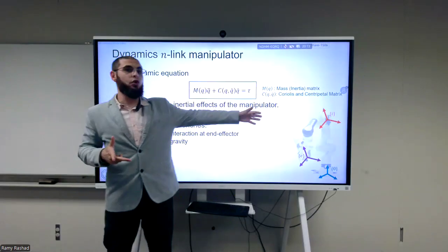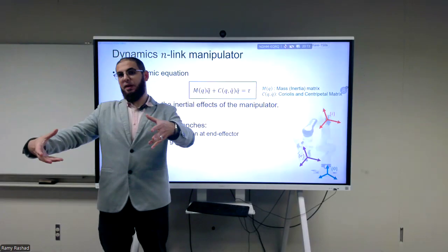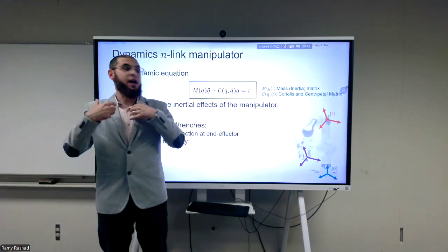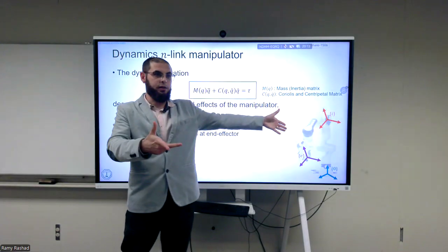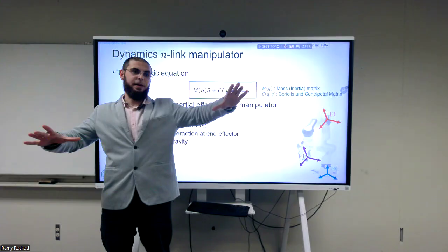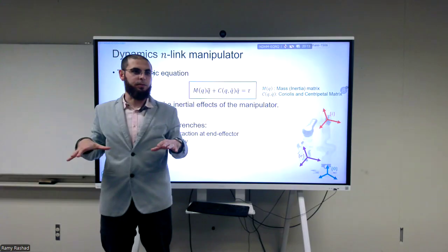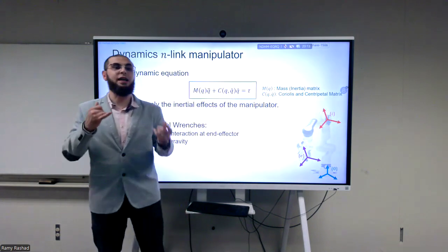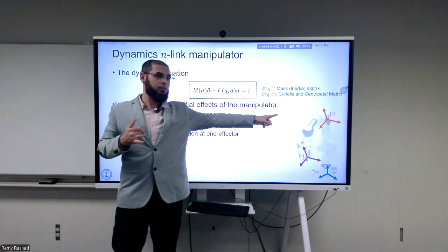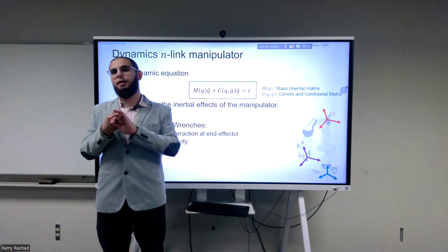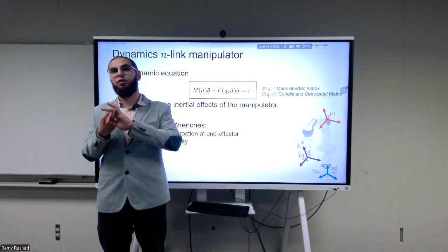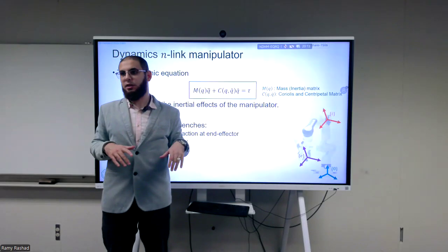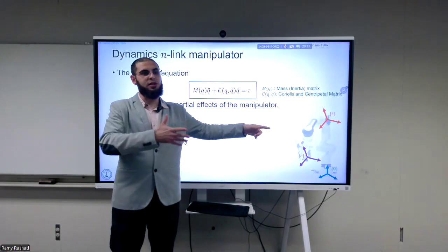orientation. If you build your robot and you take, for example, the link and you go to SolidWorks and you tell it, give me the inertia of this body expressed in my frame of choice, which is, for example, the one that you place at the joint, it will give you exactly the full 6x6 matrix, or at least the pieces that you need to build the 6x6 matrix expressed in that frame directly. Okay, so it will tell you the center of mass location in that frame. It will tell you how the inertia matrix, the J, looks in that frame, and the mass, of course, is just a constant. It doesn't care which frame it is. Okay? And then you can use this information to build it.